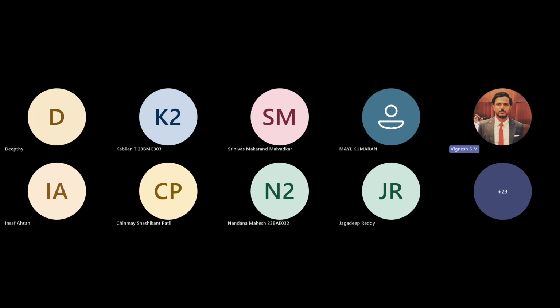So any further questions? Sir, I had one more question. Yes, ma'am. Is it advised that for a CFD analysis, the model should be a single solid body and should not contain any surface bodies or surfaces? Because we need a clean body, ma'am. Without a clean body, it will be difficult for you to have a mesh, right? That's the first thing.